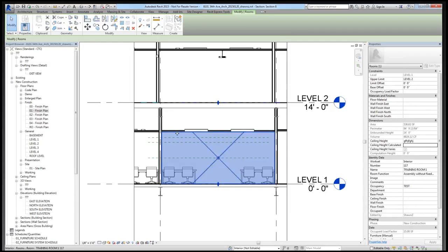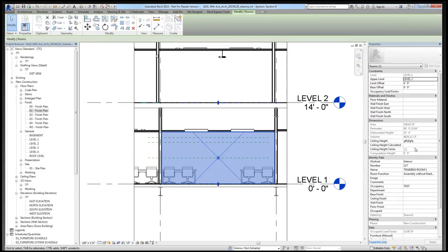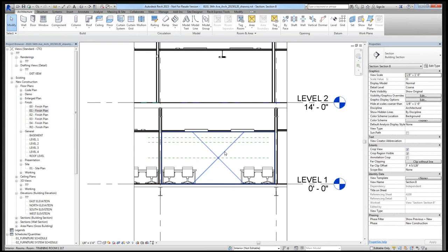And obviously, if there's multiple elevations, the interior designer or whomever can check a box that says varies, and that'll make it so that this ceiling height will think that it varies. And it'll actually report varies into the actual schedule. So I can get kind of the best of both worlds. If the ceiling height is consistent, it'll use the calculated value. Otherwise, it'll just use the basic ceiling height. That'll be something we get to in the second step, a little bit later on.